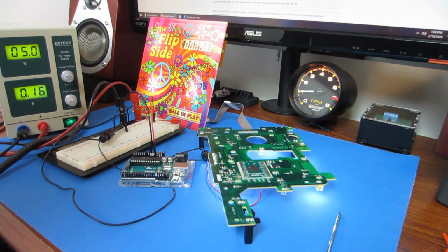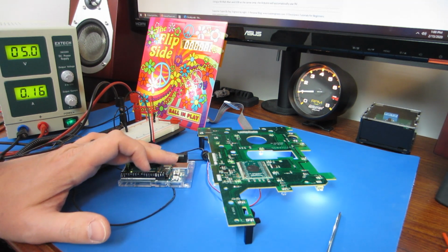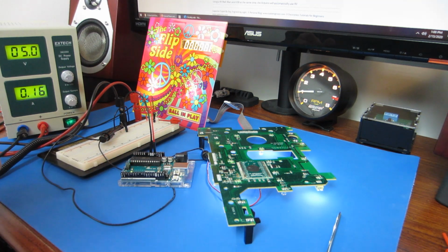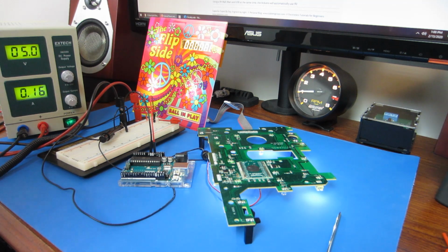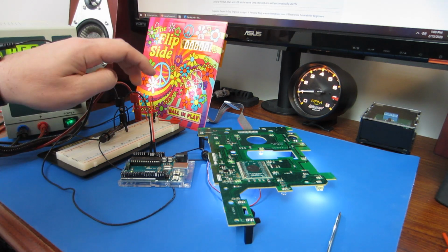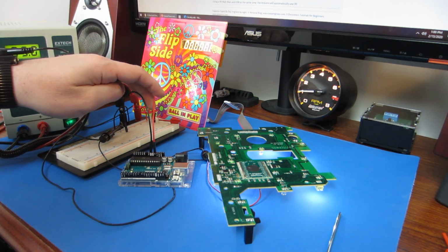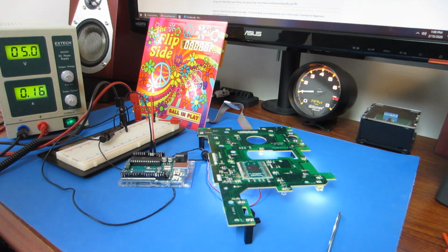It's not good for your Arduino, and it's probably not good for whatever is powering your USB, especially if that's a PC and you're trying to make a serial connection to load new software on your Arduino. So when I go to program this, I'm going to have to remember to disconnect this 5-volt connection before I plug in my USB.